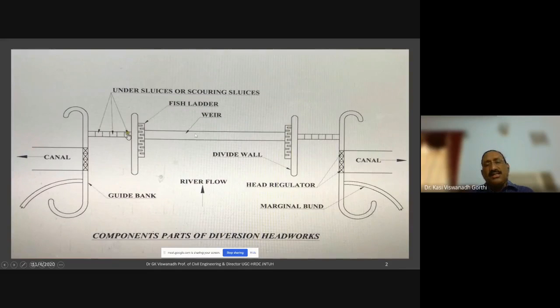So this is the weir wall, and on the upstream side, as well as on the downstream side, there will be sufficient foundation provided for resting this weir. On the upstream side, this side portion. So this is the flow direction. On this downstream side also, certain foundation is to be provided. On this foundation, this weir will be resting. So we try to see what the causes of failures of this weir are because of the flow of water, and what remedies are required to be taken.